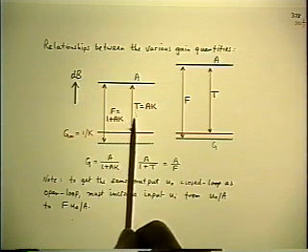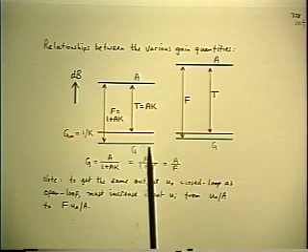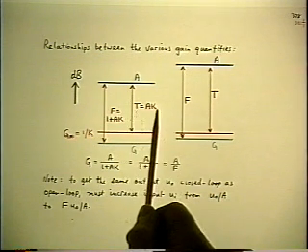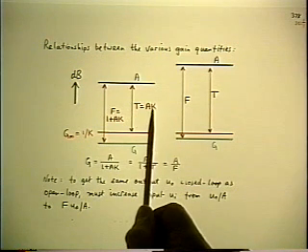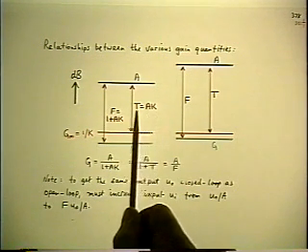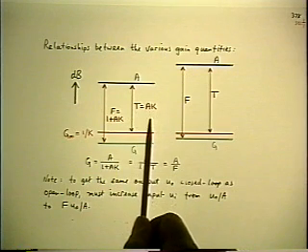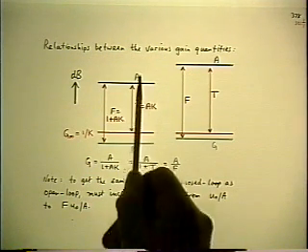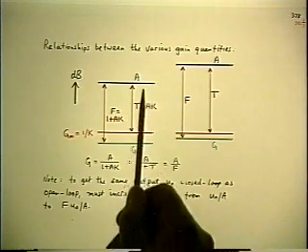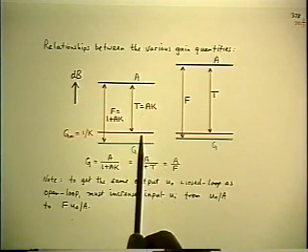Now the geometric relationships between those quantities are T is A times K. But K is 1 over G infinity. So T is A over G infinity, which is a ratio. But on the dB axis, that means T is equal to the dB difference between A and G infinity.